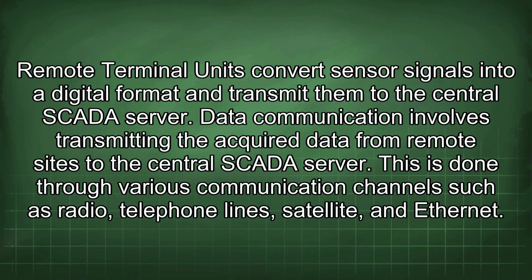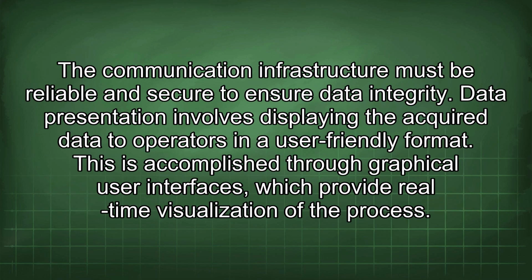Data communication involves transmitting the acquired data from remote sites to the central SCADA server. This is done through various communication channels such as radio, telephone lines, satellite, and Ethernet. The communication infrastructure must be reliable and secure to ensure data integrity.